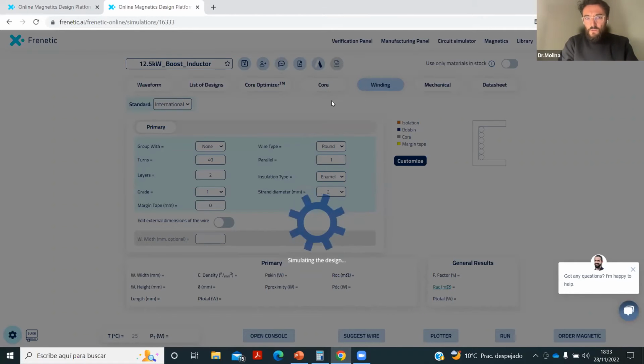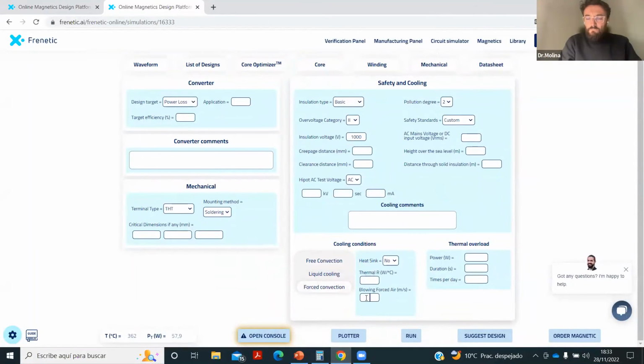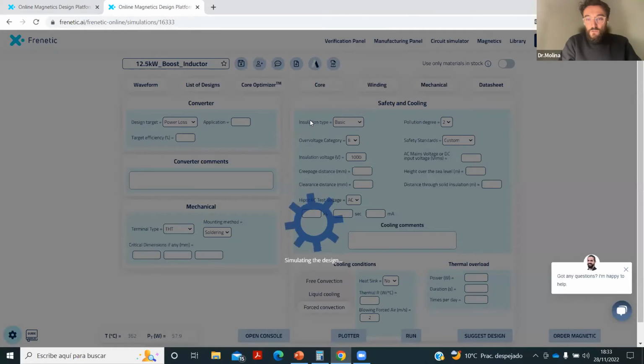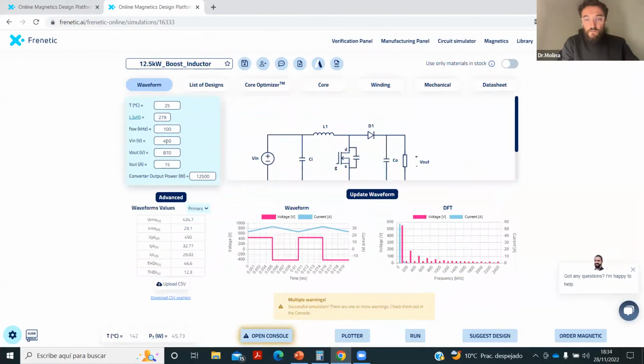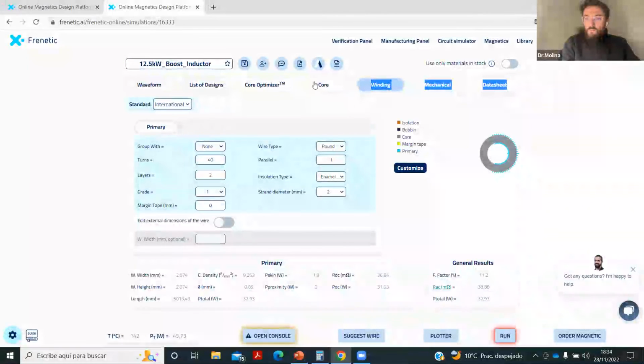I'm going to start also with some questions. In the meantime, I already answered one that was asking if the magnetic field was in millitesla, and it was yes. Tiris asked if, for the energy calculation, we have to ignore the DC bias. No, we do not, because you are basically using the instantaneous current for the energy. Then you have to take the real peak. Same thing in an AC case like this one: it is the real peak, because it's the instantaneous energy.